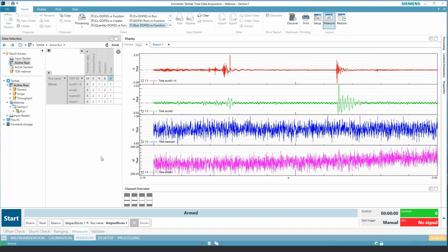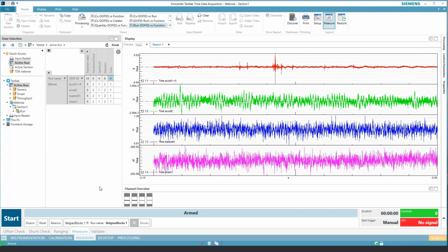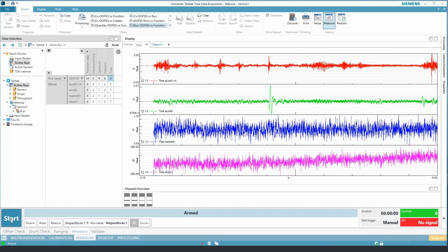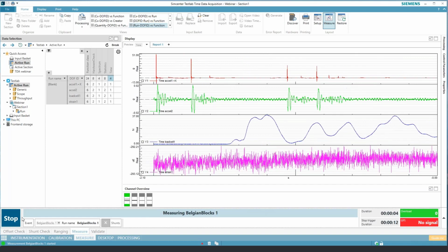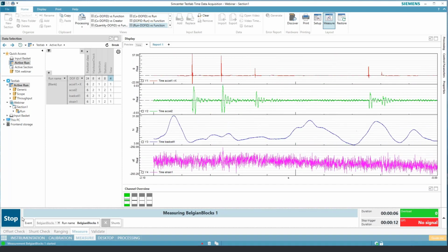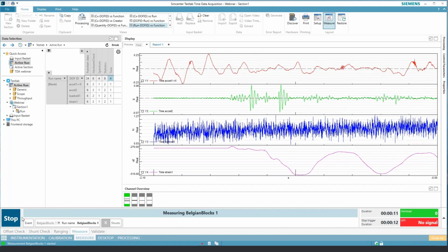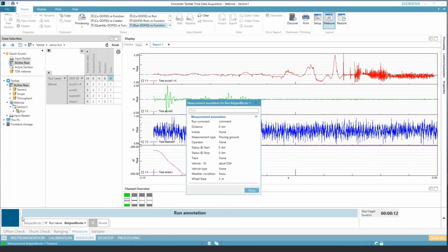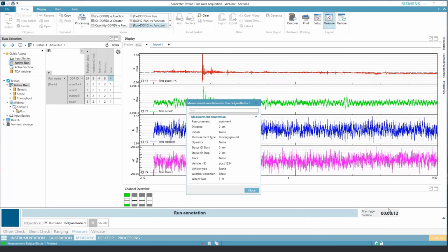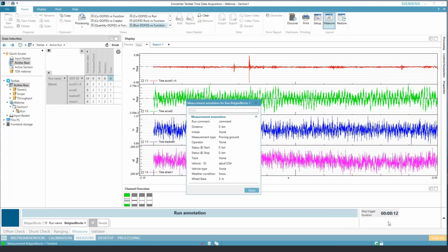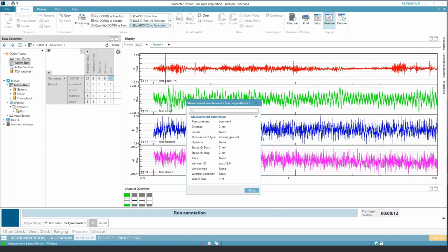I should be seeing live data coming in. I happen to be looking at an old run, my first run. So here I will hit the start, impact a couple of transducers, or basically move some of my other load cells, strain gauge, and there my 12 seconds has elapsed. I haven't pointed it out, but in the lower right corner here, you can see there was a timer for how long the acquisition was going on for, and we reached our 12-second stop time.